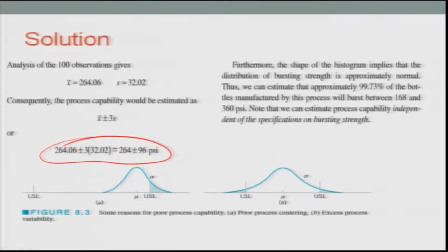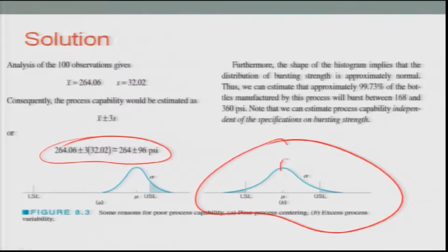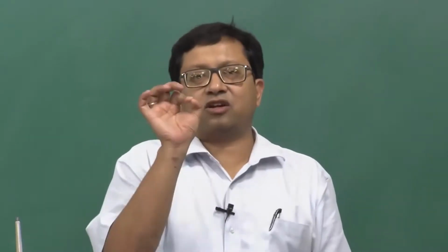So, in this second diagram which you see, the central line is given as mu, and the dispersion on to the right is given by the UCL, which is the upper control limit. Then you have the lower control limit, and depending on how the process has been done, we can find out the UCL and the LCL. Now, one thing should be remembered, the sigma value which we have pertains to the standard deviation of the process.